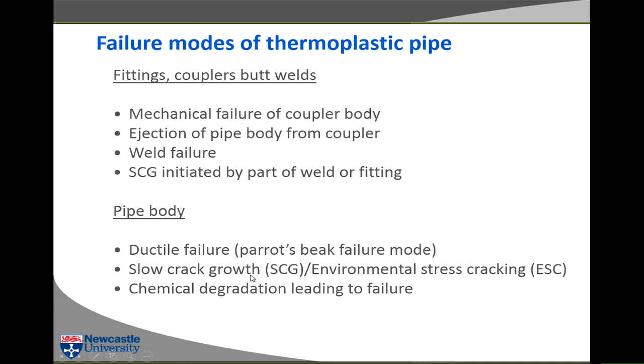So, slow crack growth is just continuous growth of a crack until it gets to a critical size. Environmental stress cracking is the same thing with the solvent present, which makes it happen more quickly. And finally, the other thing you can get is chemical degradation, which I won't talk about too much. If you transport something really nasty in the pipe, which can damage the thermoplastic, you can get actual chemical degradation of the pipe.